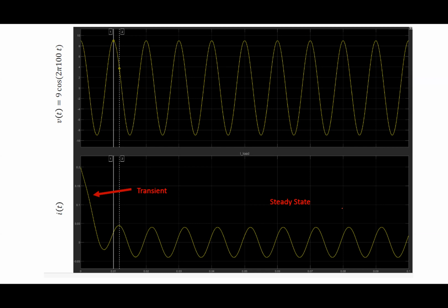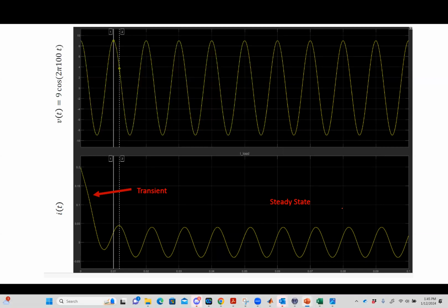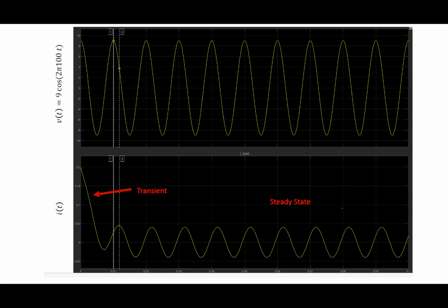All right. So what's happening? What's the transient represent? Well, it's a transient thing that goes away. What's it represent physically? Change. It's basically the opposition to change that the inductor has. The inductor wants to keep its current constant, and it can't immediately change. It sort of slowly adjusts to the new steady state. These things spend their lives in steady state, but whenever you force a transient, whenever you force some new thing to happen by changing switches or whatever, it has to slowly adjust, and that's basically what's happening.